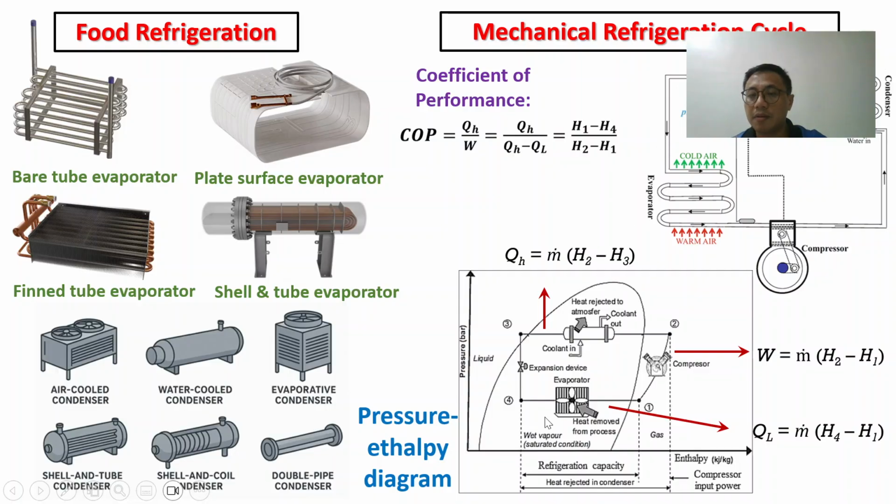The arrow here. Okay, when the refrigerant is at liquid state, you pass through the evaporator. Okay, so the enthalpy will increase, because it changes phase, right? Enthalpy will increase, but pressure and temperature still remain the same. Okay, so temperature and pressure remain the same, but the enthalpy increases because the refrigerants change phase. So now from liquid phase to vapor phase, okay, until reach here.